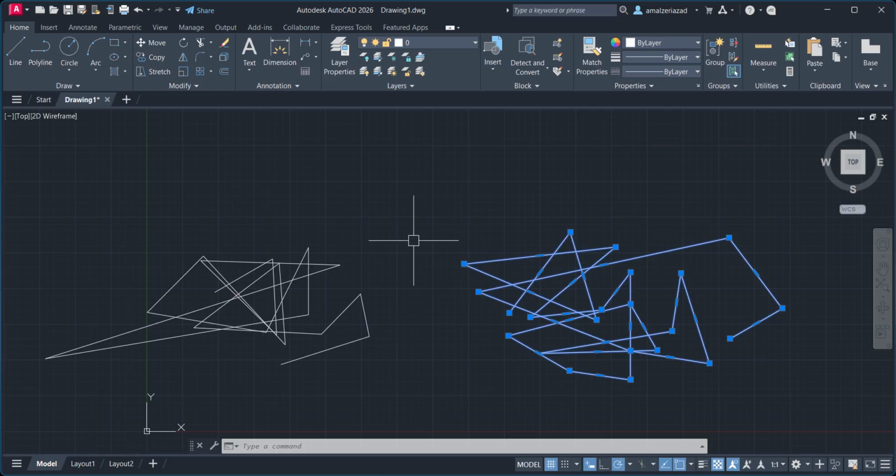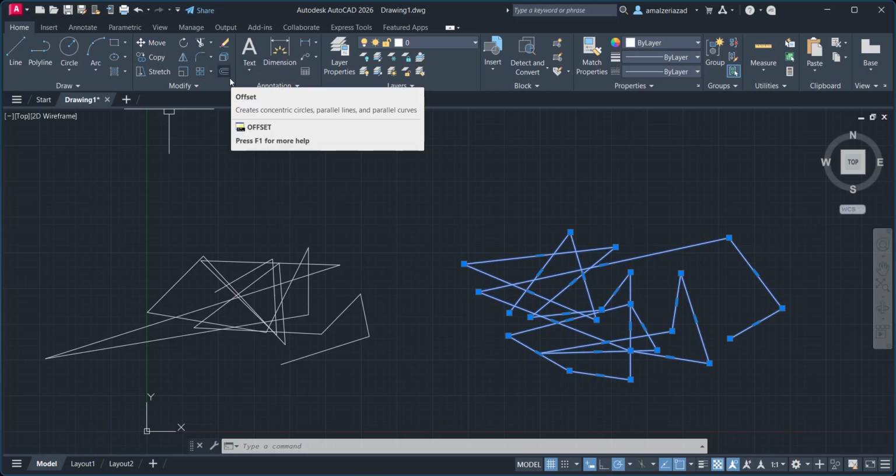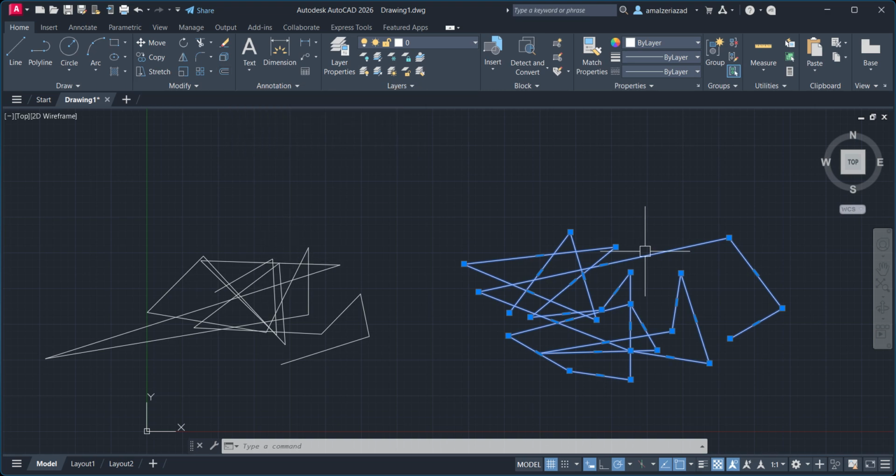The question is when we are going to use the line and when the polyline. This will vary with respect to your modification tools, particularly offset. How you want the offset will decide whether you go with line or polyline. But still, you can use both, there is no issue. Where exactly to use which, we will discuss in the practice sessions with examples.